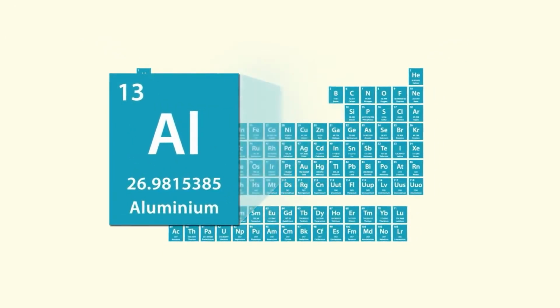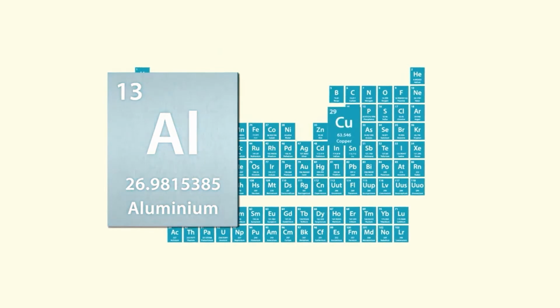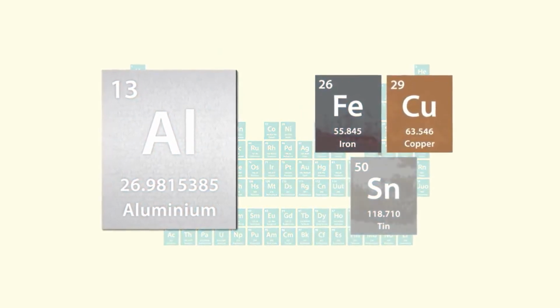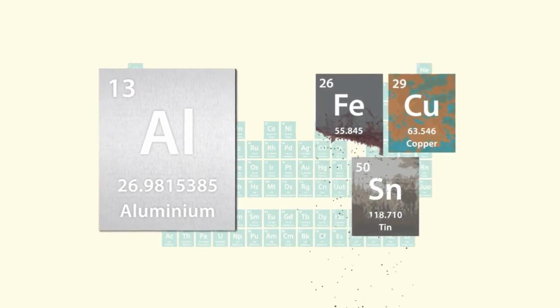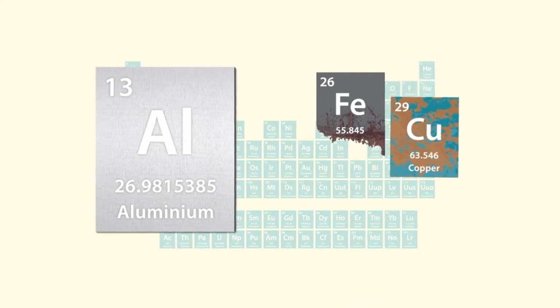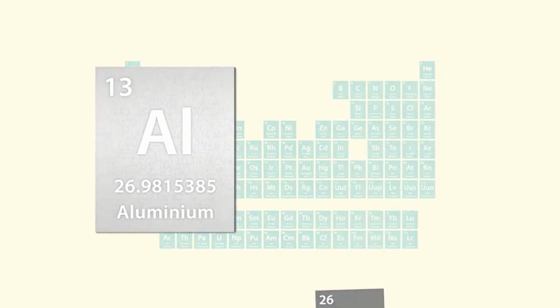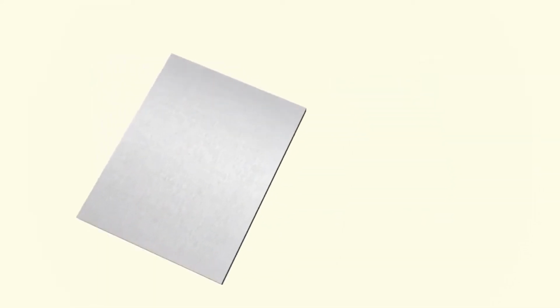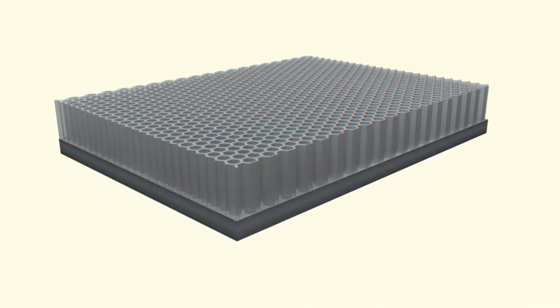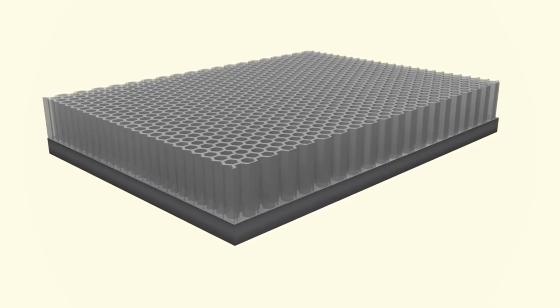Aluminum, when left out in the elements, will oxidize like iron or steel. But unlike these other metals, aluminum's oxide layer will not rust or eat away at the substrate. Instead, this oxide layer actually protects the aluminum from further corrosion. Anodizing significantly improves upon this natural occurrence through an electrochemical process that grows the anodic layer from the aluminum, aluminum oxide.